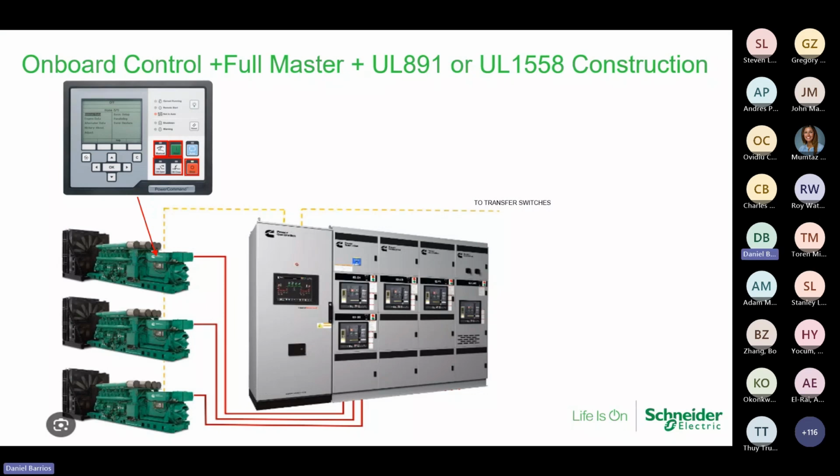Well, what got added? If you'll notice now, Cummins here has a master control section, and now they have introduced a much nicer looking HMI screen. They now add this. Each of the generators come in. The system is still being paralleled at the generator sets, and they feed into some type of a distribution board. This one is 1558 construction with draw out breakers. But now we have given you more real estate, more room. They have capacity to do additional functions should you need to.